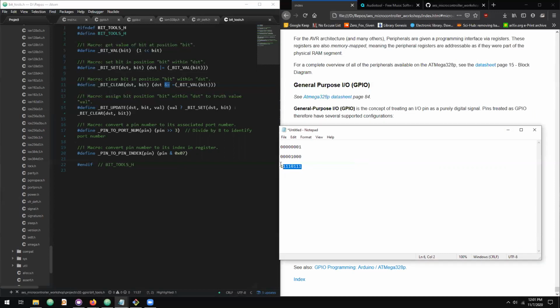So that will say that when we're doing our bitwise AND, any bit that is 1 in both the existing register value and the value we're trying to compare to, if both bit positions are 1, then the value is still 1. If the destination register has a value of 0 in some of these positions, the AND will return 0. So we are not changing our register value in that case.